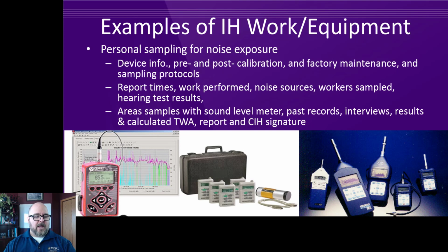On the left, we have equipment that you actually put on the worker, and then you put the microphone within 6 inches of the ear, and then they wear it all day, and it monitors all the different noise levels they're exposed to and data logs it, and then you can download it.